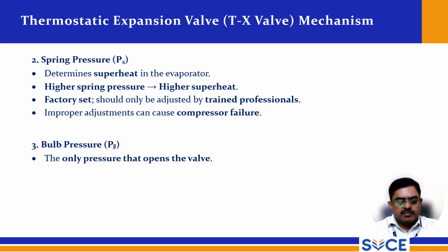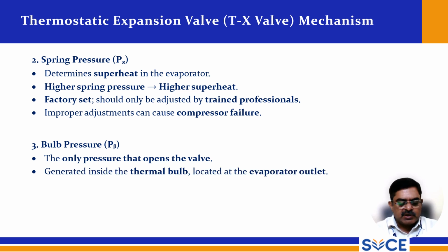And bulb pressure is the only pressure that opens the valve. It is responsible for opening the valve and is generated inside the thermal bulb located at the evaporator outlet. So higher bulb pressure means more refrigerant flow.